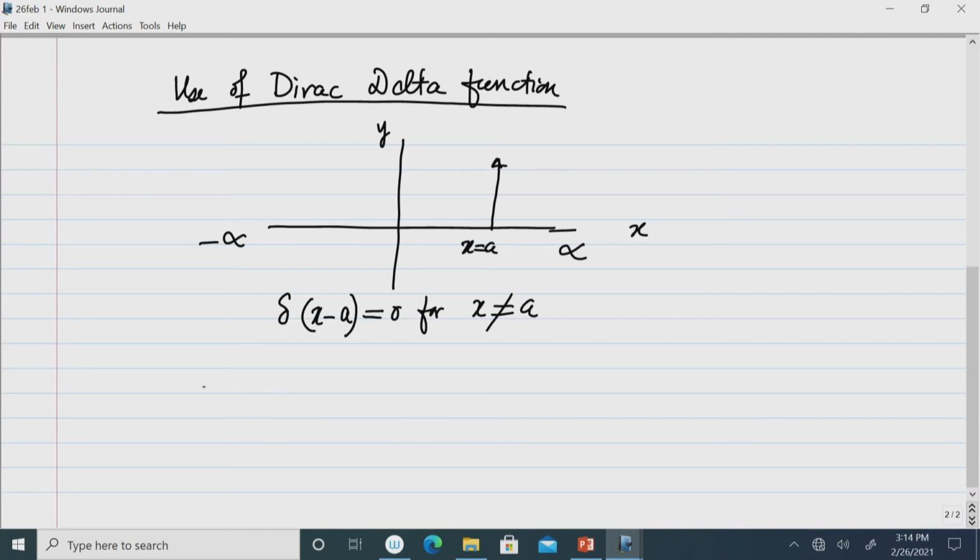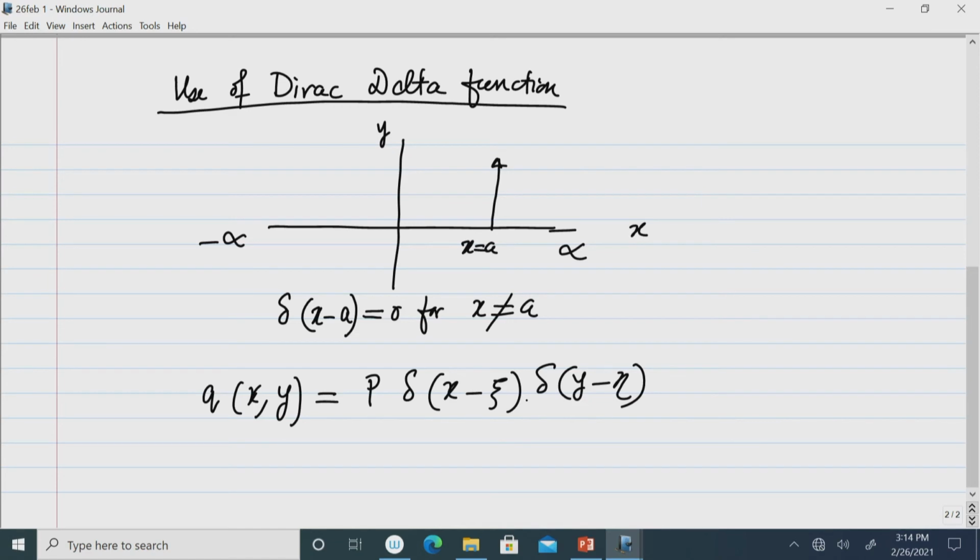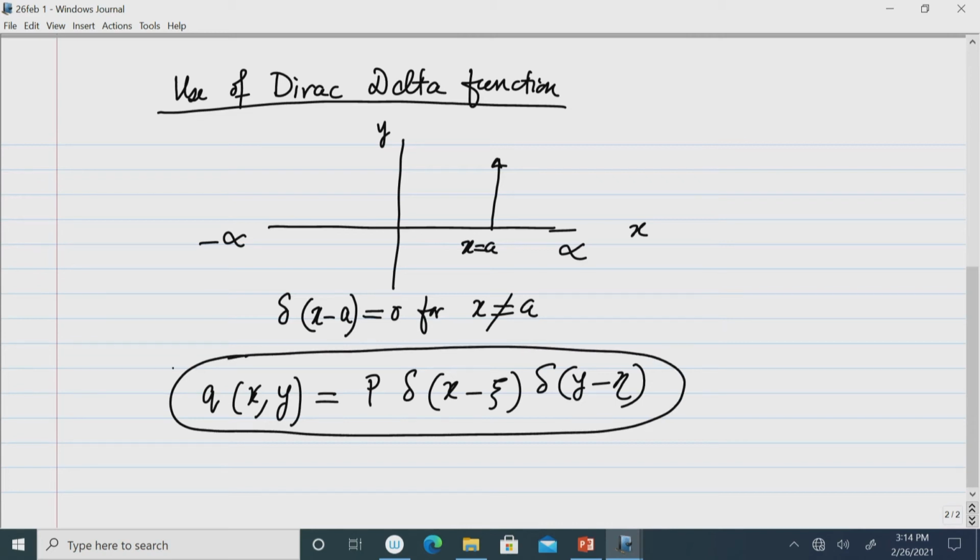load on the plate. So, the equivalent distributed load in the plate subjected to the concentrated load, we can write as, suppose the load is acting at the coordinate here, x coordinate is xi and y coordinate is eta. So, the q x is now expressed here like that. The Dirac delta function has a very important property, use of which the calculations are simplified. So, the properties of the Dirac delta function that are used to simplify the calculation are these.